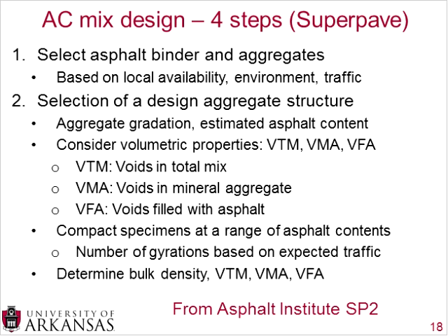And three terms that you will need to be aware of during this process are your VTM, your voids in total mix, which is the same thing as air voids, your VMA, your voids in mineral aggregate, and your VFA, your voids filled with asphalt. So as you go through the process, you track these three quantities in order to make sure the mix that you're designing is matching those properties.